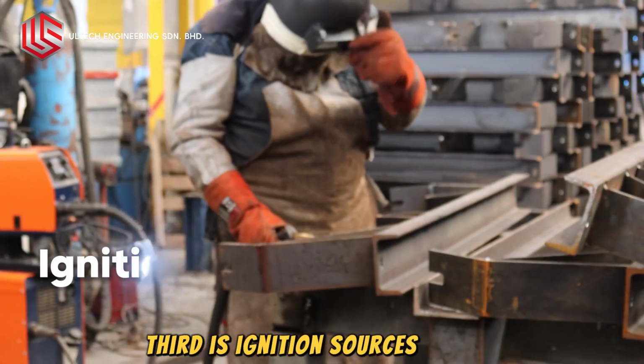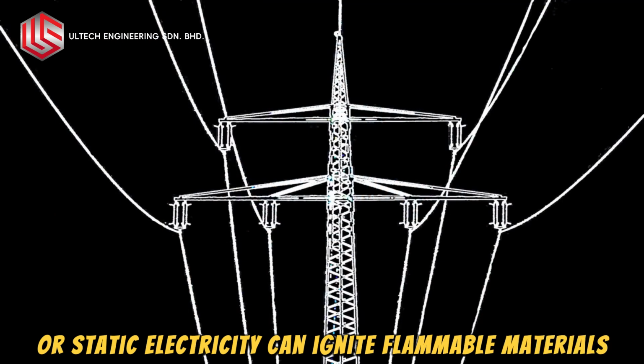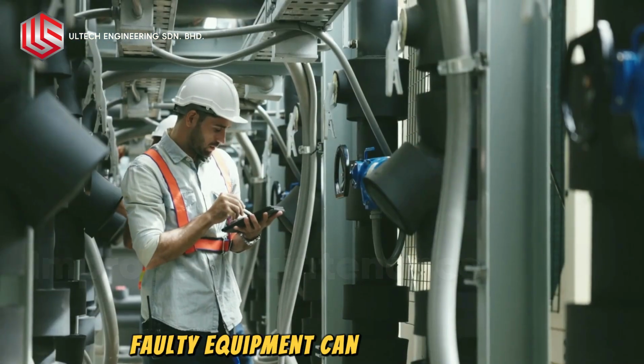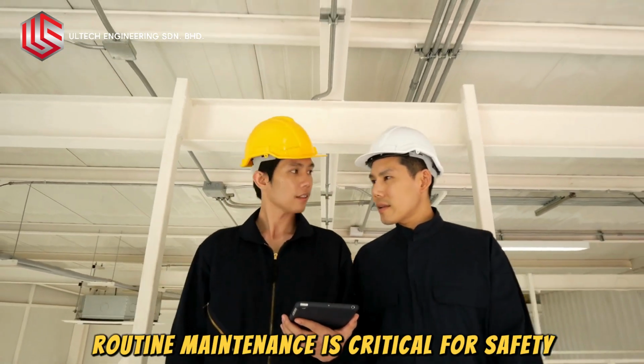Third is ignition sources. Sparks, hot surfaces, or static electricity can ignite flammable materials if not controlled. Fourth is improper maintenance. Faulty equipment can spark or leak, increasing risks. Routine maintenance is critical for safety.